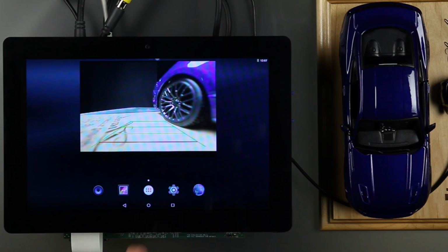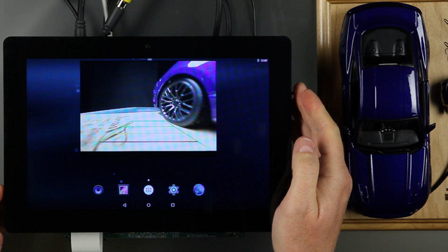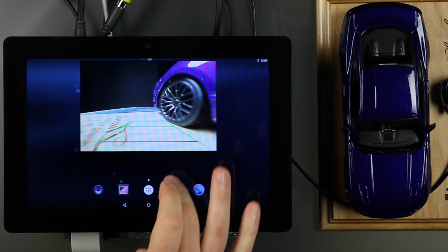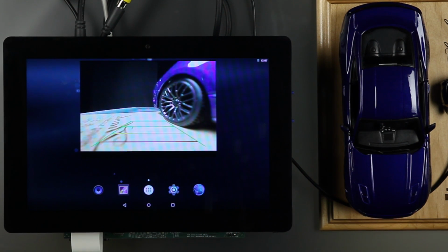Finally, I would like to show you how our rearview camera solution withstands a complete crash of the infotainment operating system. I can force a crash of the kernel underlying the Android OS like this. You can now see that I no longer get any updates of the Android Live wallpaper layer that was showing the bubbles moving back and forth here. I can no longer manipulate the Android UI either.